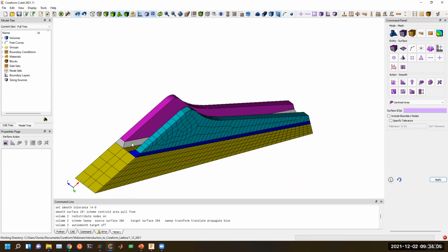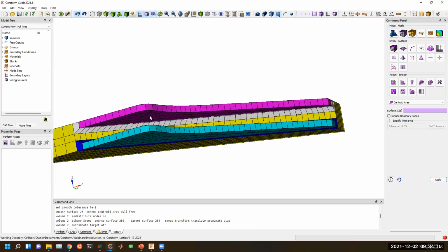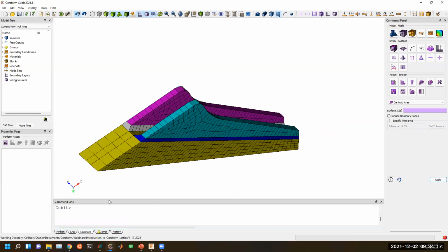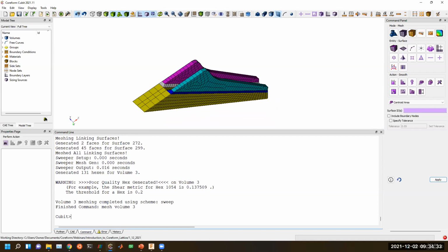As well as then these final 2 volumes on the other side. Once we've built our mesh layout, we can build a U-spline. Right now we build U-splines only through the command line. We don't have a GUI interface for it. We can set our U-spline degree and continuity and build it. And in the sake of time, I'm not going to run those commands.